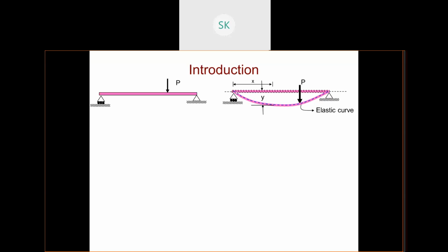If you see, there is no deflection at the support because these points are hinged. This has been given a hinge support. Always remember, if someone asks you in the exam or an MCQ comes in your competitive exam what the deflection at the support is, it will be automatic. Don't get confused. Deflection at the support is always 0, okay?